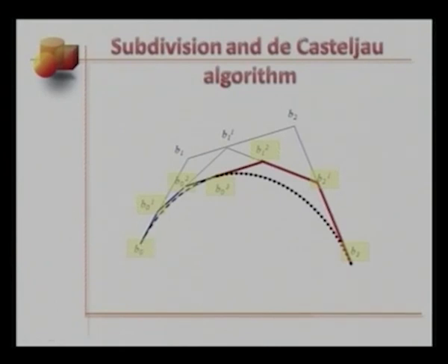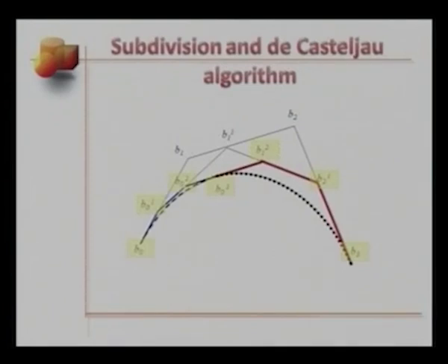Only if I move this control point here, identified by P sub n or Q sub 0, because both these points are the same, I would witness the shape change in both segments, this one and this one. So in a way, would you agree with me that subdivision introduces local shape change features in the original Bezier segment? If I were you, I would say yes.